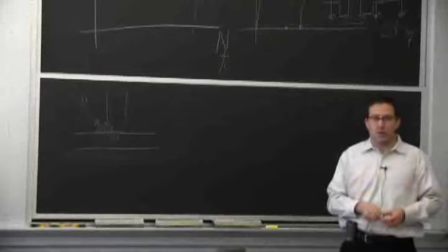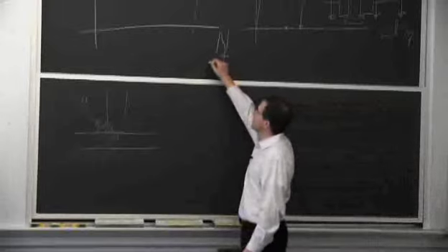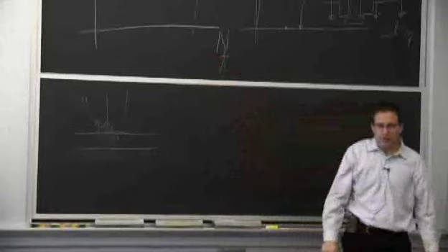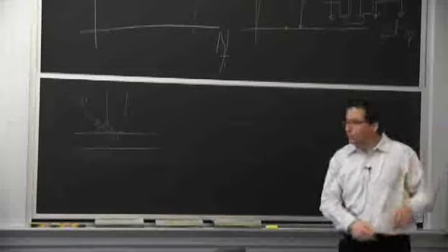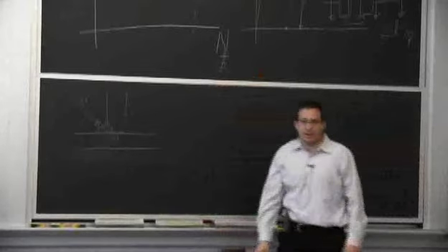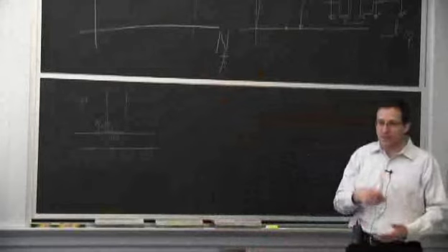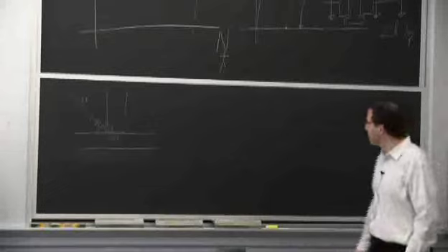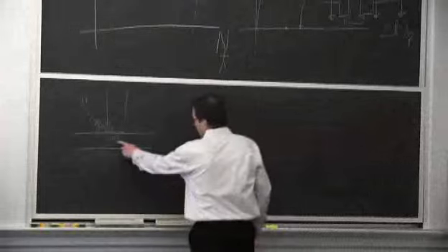So it's one of those properties, probably I should have said it last class, that normally if you raise the yield strength, you'll raise that fatigue limit over there. Not always. I mean, we're talking about trends here, so you have some idea of what to expect. You always want to verify. So that's the heat affected zone right here.